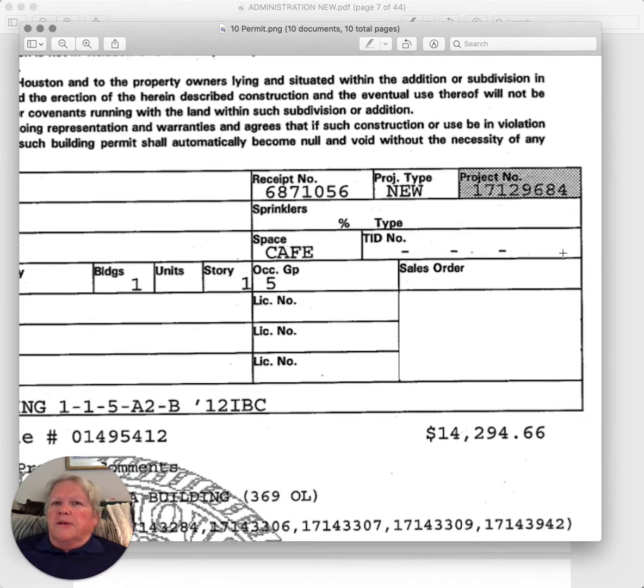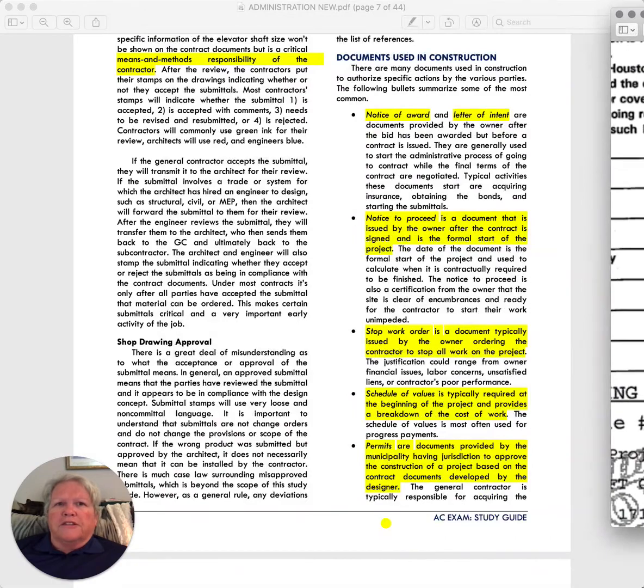And what's critical about permits is that you've got to close them out. Sometimes subcontractors will pull permits on a job and then fail to notify the general contractor, and you think you can close out a project, but there's one open. So you have to be mindful of tracking all the permits that you get on a project, which is why this is brought up.